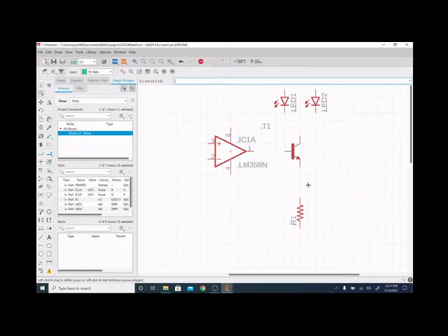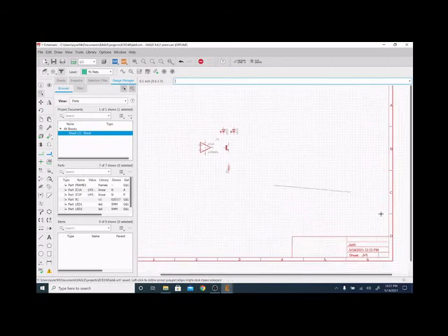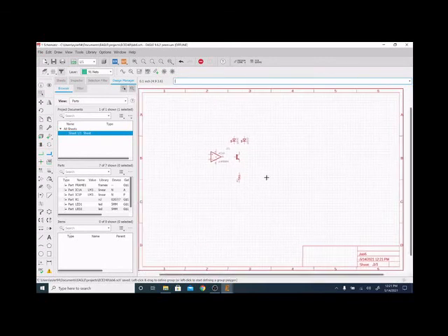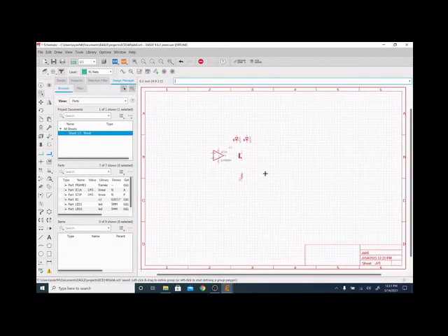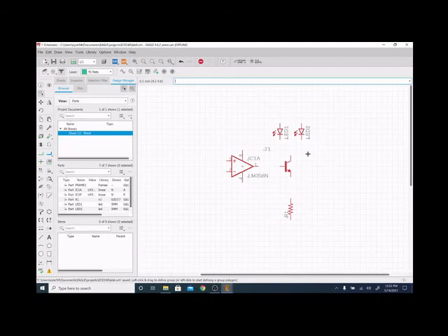All right, I almost forgot. Before we switch over to the library, we need to save our work, because if something happens, we will regret it. So you can see I just hit Control S, or you can hit the save button, and it auto updates the time. It's 12:21. That's all good. By the way, to pan, I'm holding down my middle mouse button. This should have been mentioned earlier, but please don't use Eagle without an external mouse. You can, and that's fine, but it gets really rough really quick.